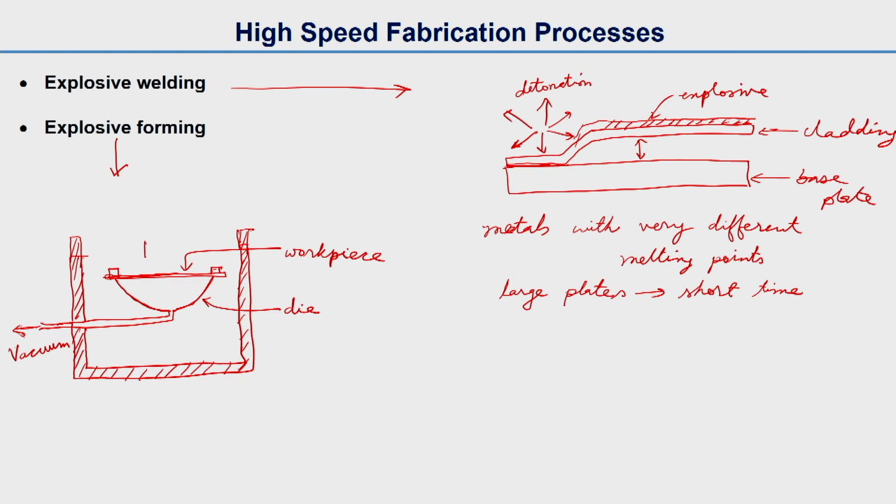We will have an explosive in here. Generally the explosive is not in direct contact with the workpiece, so we will have water in this. Water is a transferring medium for the shock waves. So a shock wave will be generated. The water is the shock transfer medium.